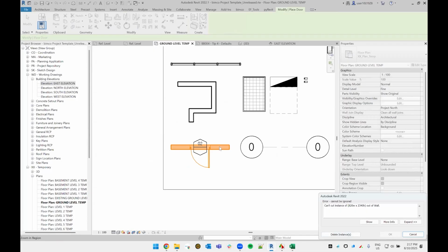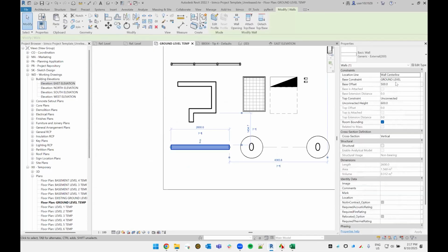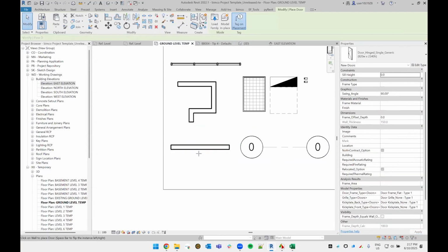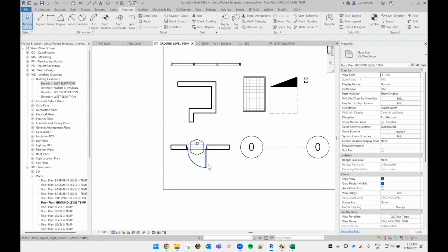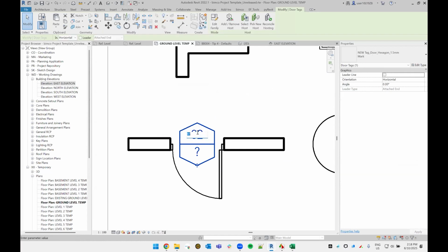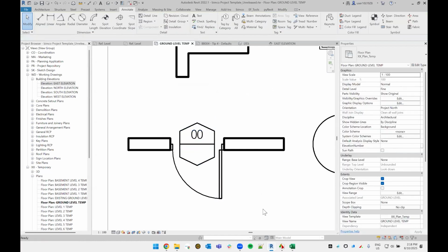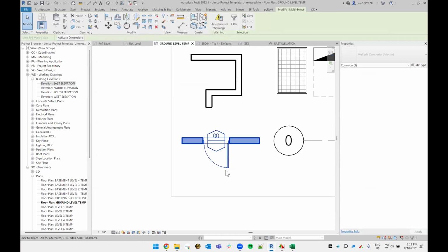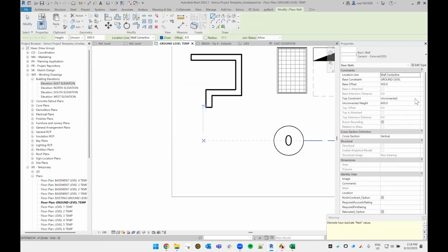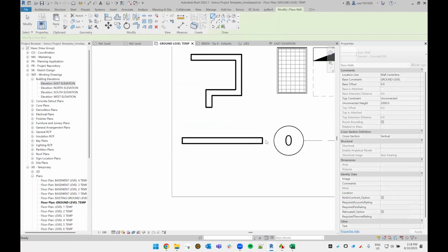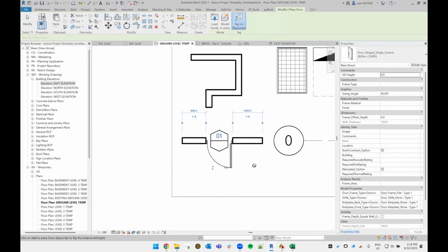And that's also having issues because that wall's drawn at a very strange height because I haven't fixed it. So door 2, it's coming in as 2. If you want to get that back to the default, place a door, set it to 0, delete it. And then the next person who goes to draw will have a door that comes in as 1, like so.